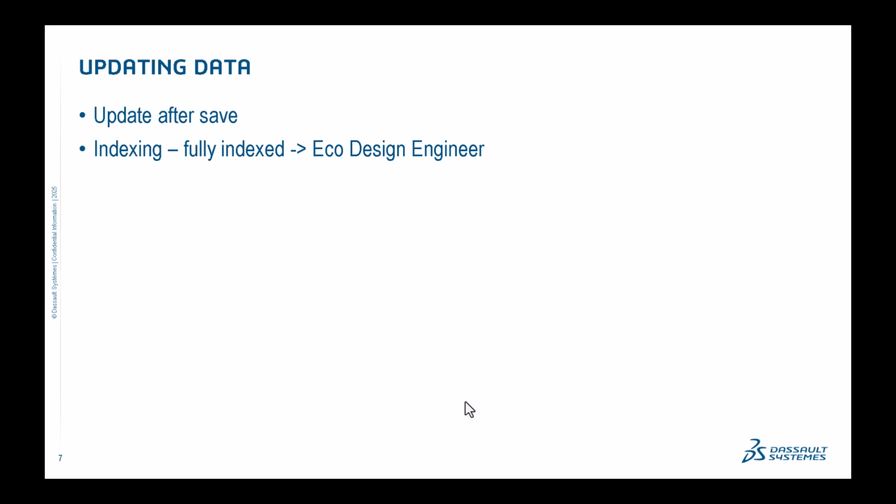This process also ensures that the mass properties information of your SOLIDWORKS models is accessible to the applications within the Eco Design Engineer role. After you save your SOLIDWORKS model, it does take some time to index, and the time that it takes to index your SOLIDWORKS models is dependent on many factors, including the size of the models and the number of components within an assembly, and many other factors.